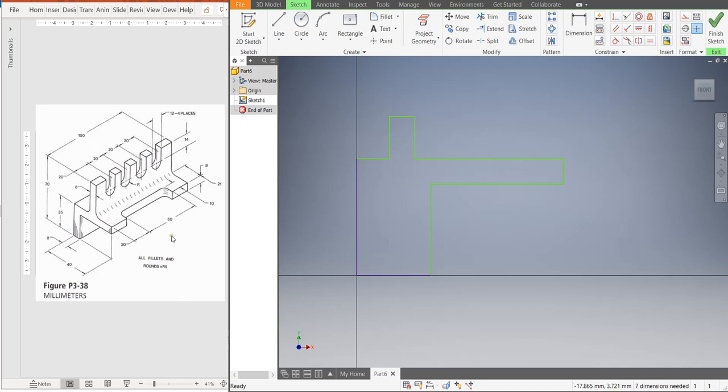Okay, next we can add equal constraint, because this height is 8 and this thickness is 8, this thickness is 8, this thickness is 8. So let me write equal constraint, this one equal to this one equal to this one, and in this case we have to just put dimension for one of them like this. Equal again, this line equal to this line equal to this line.